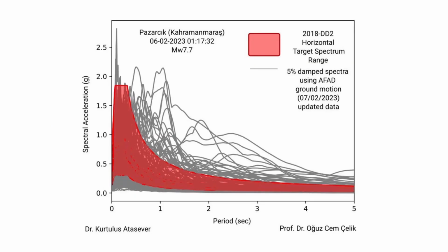Similarly, there are many other stations from where the strong motion records and data are fetched and the corresponding spectral accelerations are plotted. So this is the graph where all the spectral accelerations from various stations are put together, and these are all compared with the target design response spectrum specified by the code. Now here you can see that in most of the cases the spectral acceleration exceeds the design response spectrum.